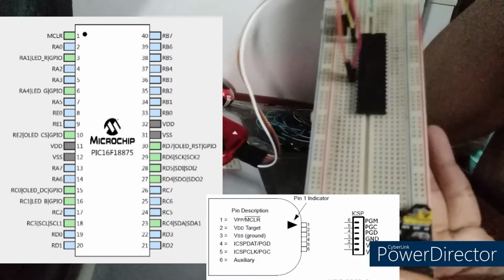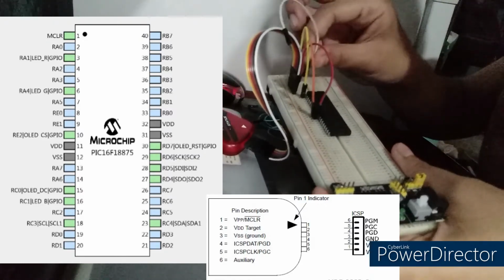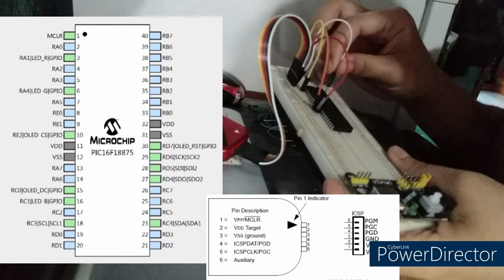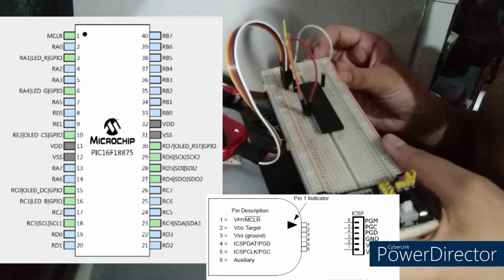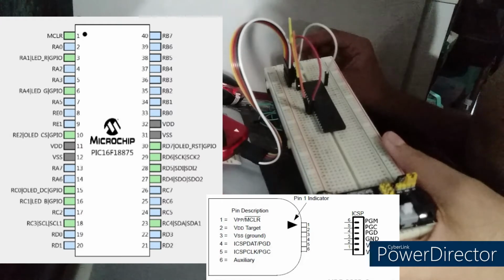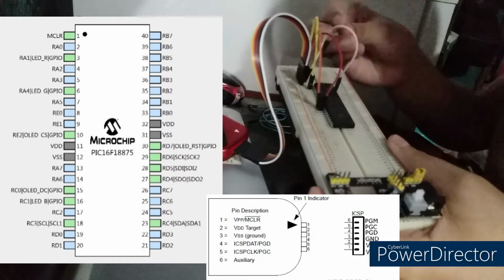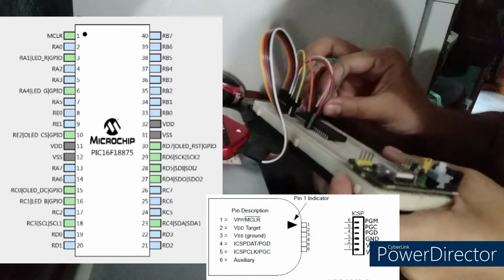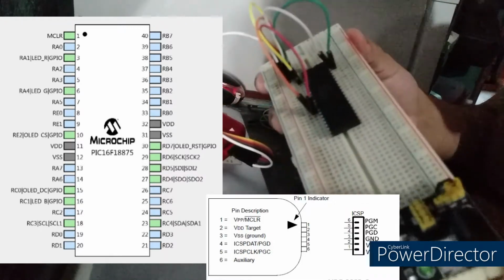So that's our connection. Now let's connect the PGD of our PICkit 3 to our 40 slot, okay, to the 40 slot of our IC, on the other side of our IC. And then let's connect our PGC, or the 5th pin of our PICkit, to our 39 slot. That's the black color. So let's connect it using this green wire here, to the 39 slot of our IC. So this will be our connection, and we will be connecting this to our MPLAB software.